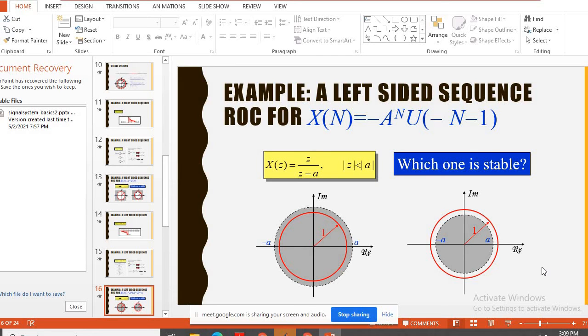So this is the effect. Earlier the unit circle was included. Now look how it appears here: this is your z, the a one, and here the circle. So the region of convergence was outside it, and here it comes inside it. So that is the difference. z must be less than a. Suppose this is the a limit, it should be less than that. So it is inside, understand, it is not outside, it is inside. Okay, earlier it was outside, now it is inside. So that is the difference, inner side, outer side. So for left sided sequence it is inside. For right sided sequence it is outside. That is the exterior part of the unit circle, and this is the interior part of the unit circle. So this you have to remember.